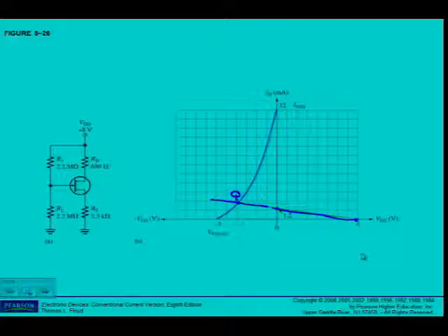And then what you're going to do further, because I only look at this graph, I don't look at your calculations, I want to see on this graph that you know what you're doing. Then you will draw a broken line to show me the parameters for the Q point, the values of ID and VGS. And I can see here, in this case, ID is equal to 1,8 milliamps and VGS is minus 1,8 volts. I just want to stress again, you have to include all the labeling.